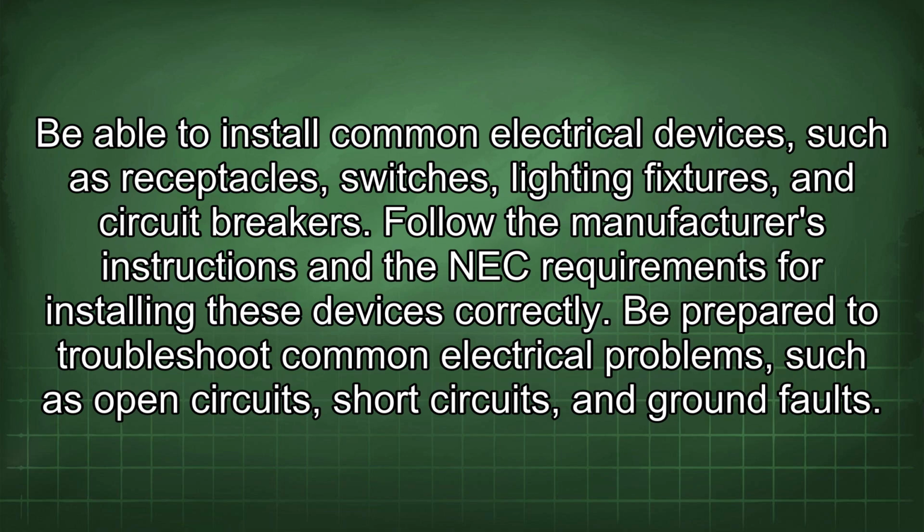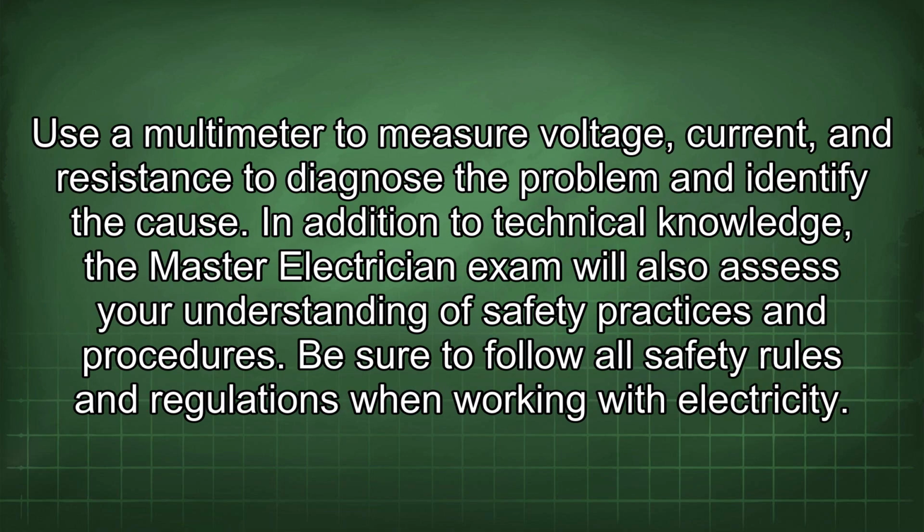Be able to install common electrical devices, such as receptacles, switches, lighting fixtures, and circuit breakers. Follow the manufacturer's instructions and the NEC requirements for installing these devices correctly. Be prepared to troubleshoot common electrical problems such as open circuits, short circuits, and ground faults. Use a multimeter to measure voltage, current, and resistance to diagnose the problem and identify the cause.